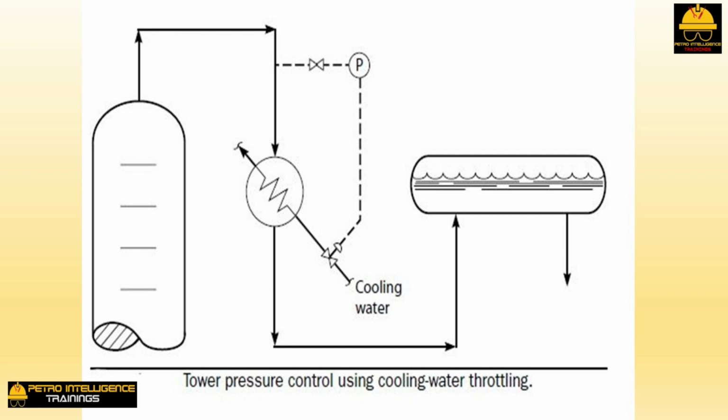Throttling on the cooling water works fine, as far as pressure control is concerned. But if the water flow is restricted too much, the cooling water outlet temperature may exceed 125 to 135 degrees Fahrenheit. In this temperature range, water hardness deposits plate out inside the tubes. Then the heat transfer coefficient is permanently reduced by the fouling deposits.